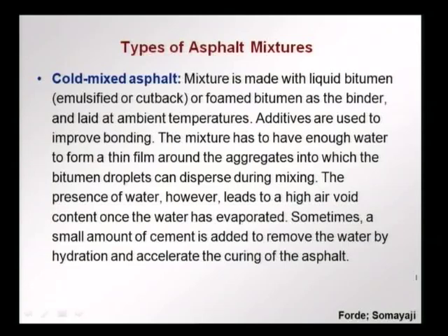Here what happens is that the mixture of the cold mix asphalt has enough water to form a thin film around the aggregates, and as the bitumen particles are dispersed in this water, the droplets now spread in this film of water that is around the aggregates and reach all the different surfaces that have to be wetted.